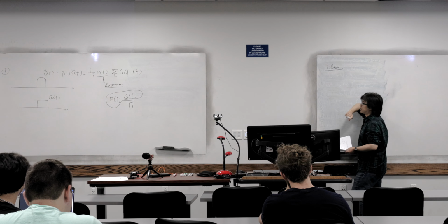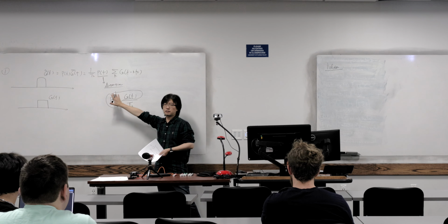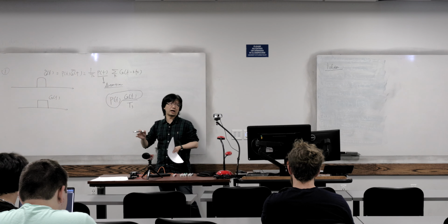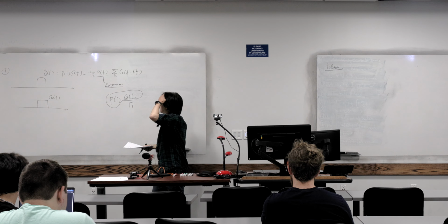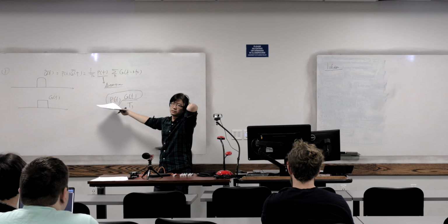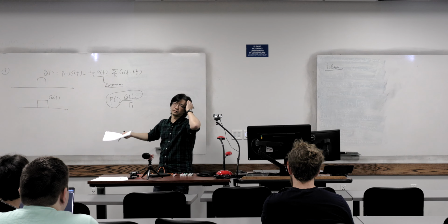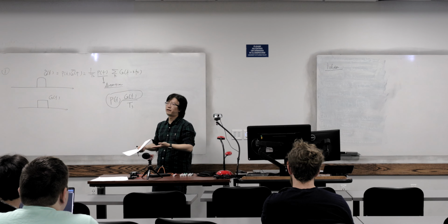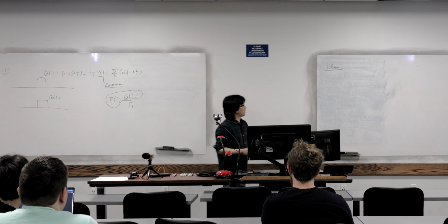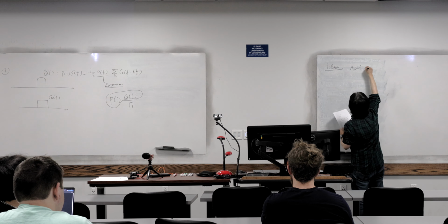So the approach to undo the impact of it is called equalizer, okay? And you may have heard of this word many, many times in communication, right? For example, if we consider wireless communication, this function could be a channel, right? How to get rid of the impact of the channel? We use the equalizer. How to design the equalizer? Just divide it by the channel, right? That's it.